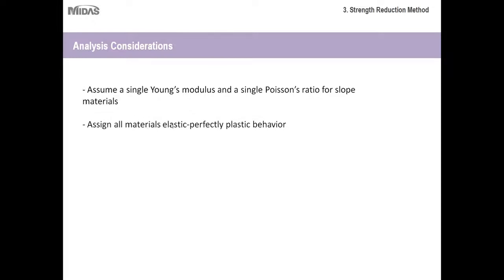Assign all materials elastic perfectly plastic behavior. That's pretty straightforward. Obviously, if you want to calculate the deformation, it's really important to assign it this type of behavior.